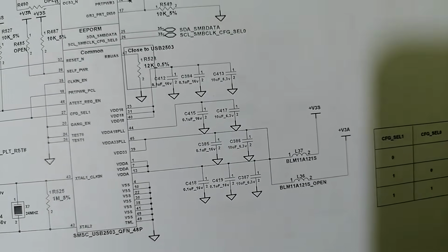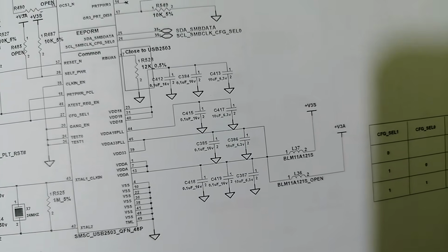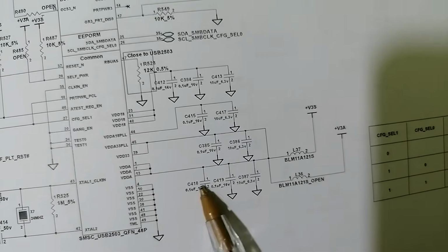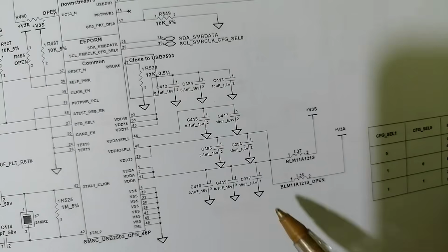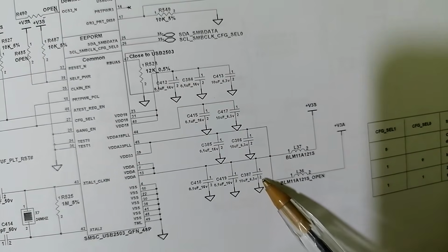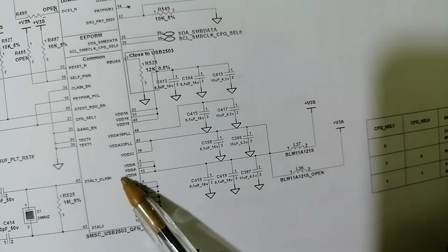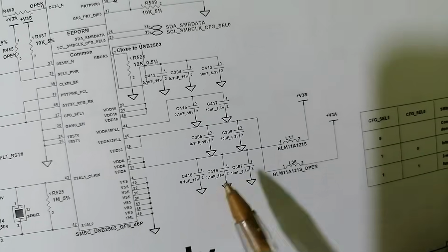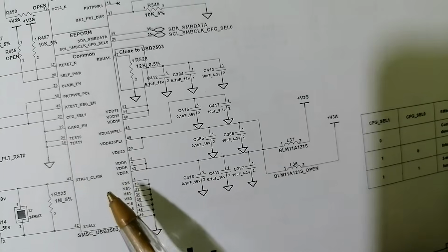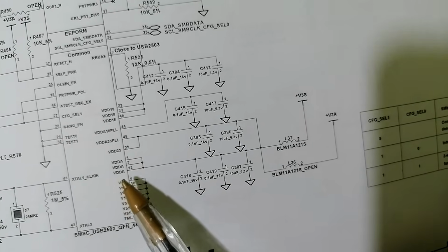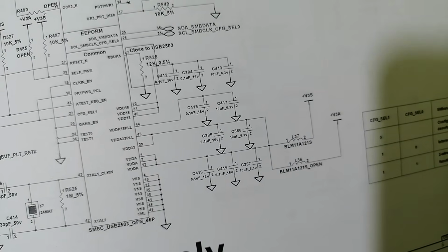As I told you before in the previous videos, this is basically an IC. Next to each IC, you will find many ceramic capacitors. The ceramic capacitors are always connected to the ground on one side, and connected to the IC on the other side. That's why if you find, for example, that these 3 ceramic capacitors are shorted, it means the IC is shorted. So this is the second method that we use to check the serviceability of an IC.